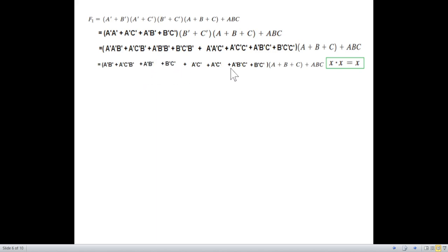So this way you get this equation. Now further, we'll use the relation that if there are two of the same with the plus sign or OR gate, then we can write just one. So let's see here, A dash, B dash, A dash, B dash twice, so we'll just write one. And similarly the other terms. The duplicates I have crossed. You can check them.